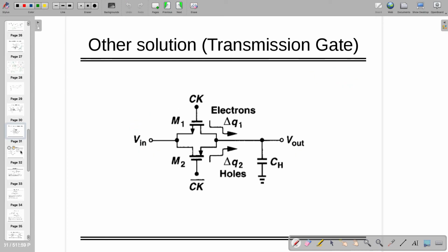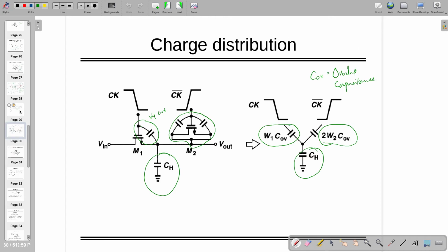This model. So you have to make sure that whatever W1 is there, if W2 is equal to half of W1, then this capacitor will be the same. That is the reason why you have to be careful, otherwise you will be inviting more problems, right? One more time, when you have this, you are going to have kT by C noise. Adding one transistor adds kT by C, and flicker noise is coming because of those things. You cannot stop them. So this is how you need to work.